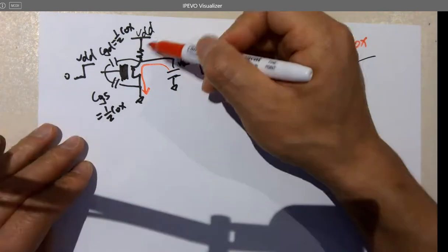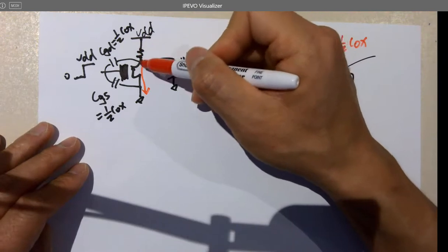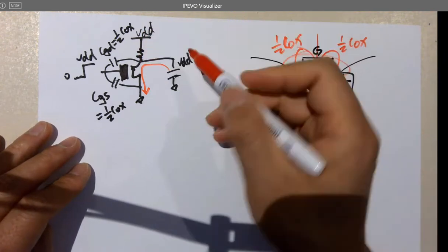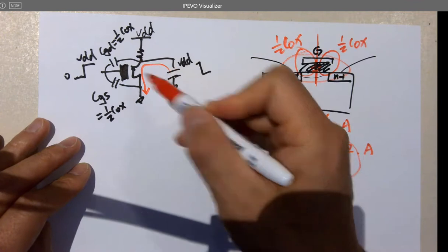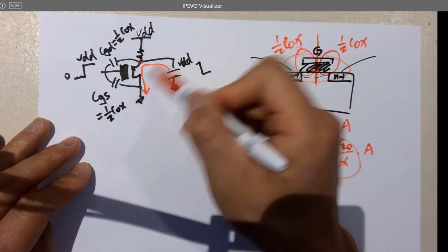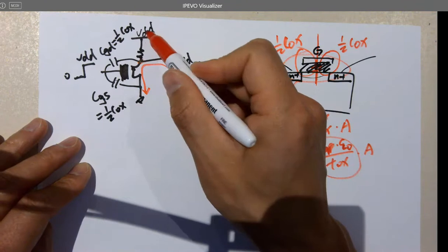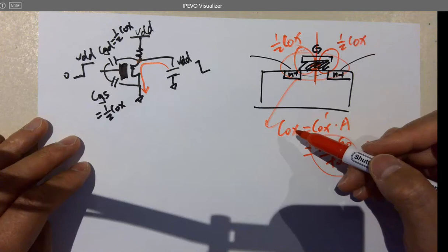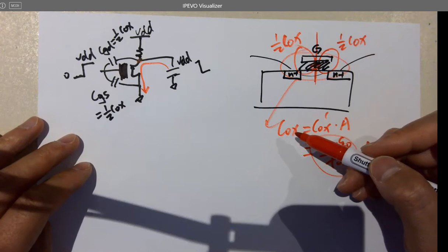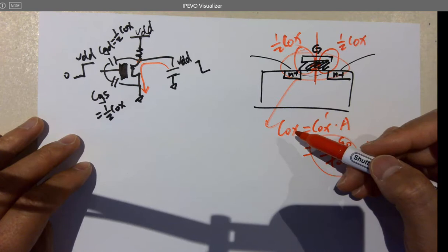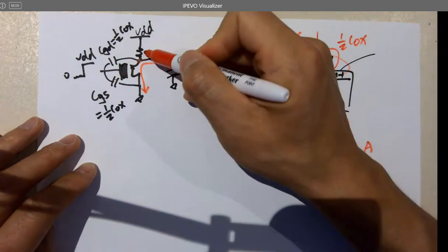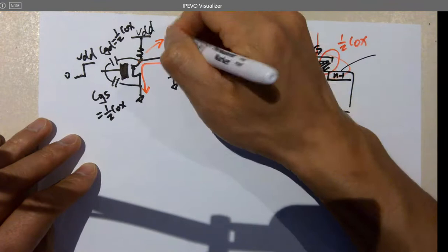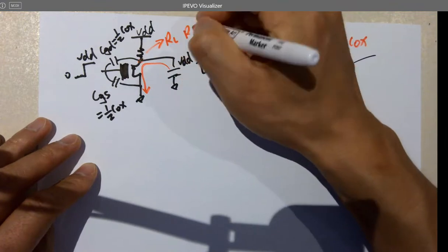That would raise the question, hey, it's still connected to the VDD through the resistor. So why, when the transistor channel is on, is this point going to be discharged instead of being pulled up to VDD? Resistance, right? Which one is easier? Going down is easier. That's why it's shorted to the ground, not VDD. Okay. What's the name of this resistor? Is that RL or R pull up?